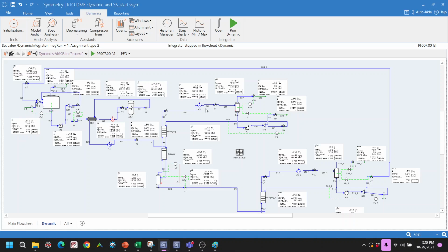Then it goes to the condenser and the flash drum, where we have gases out if there are any, and then the reflux. The DME is obtained from the distillate stream of this DME column, and this is the reboiler, where we separate the DME. So we are left with water and methanol.